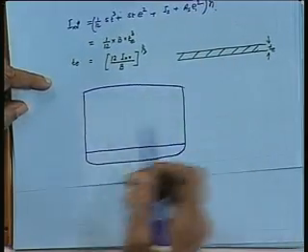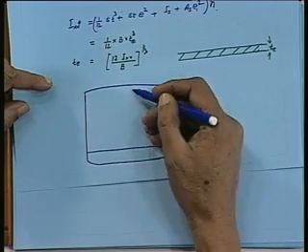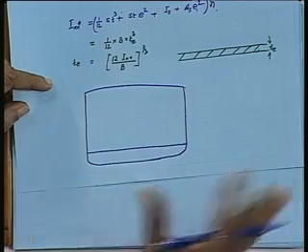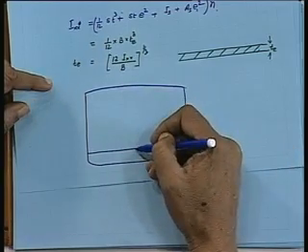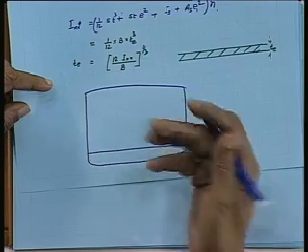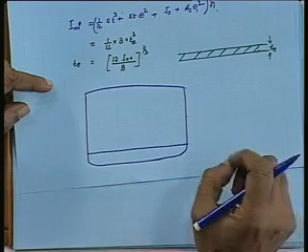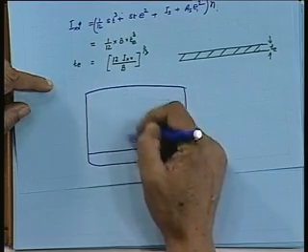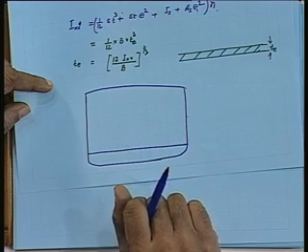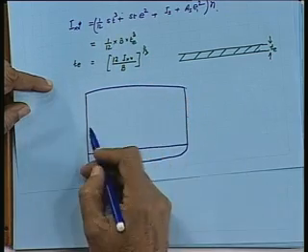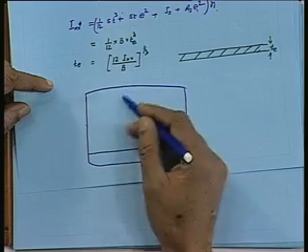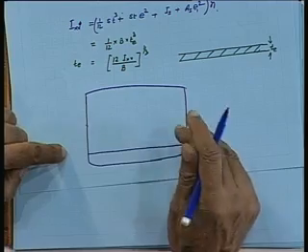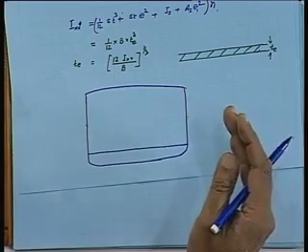Before that, let me also say why we don't have the horizontal one. Now, we have seen that more or less the depth here is half the beam of the vessel usually. So, this span works out to be less, and if you see the bending moment expression, you will find that the maximum bending moment is proportional to the span square. Okay. So, now if this is your D and this is of the order of 2D, so if you are putting a particular stiffener here, your span is becoming twice, and square of that means 4 times.